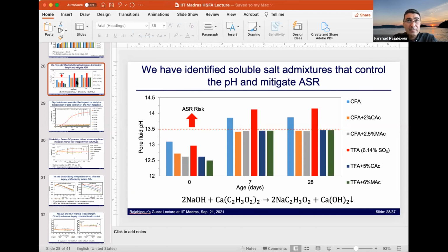That coincided with the reduced supply of pozzolans. So there is an ongoing question of what we can do to mitigate ASR. At the same time, the other solution, lithium admixtures, is in high demand by the battery industry. So there is a vacuum of technologies to address ASR in case a pozzolan is not available, or maybe to improve marginal pozzolans to help them in mitigating ASR.